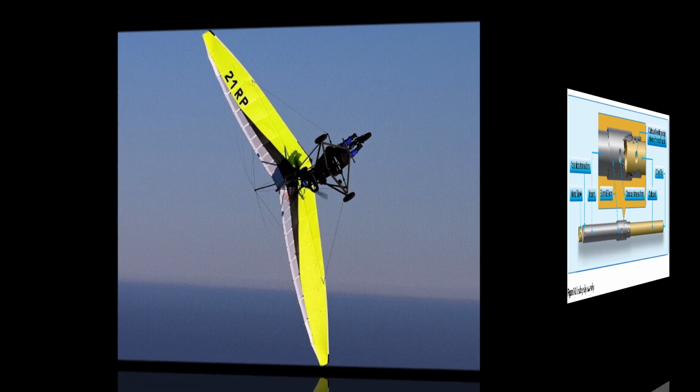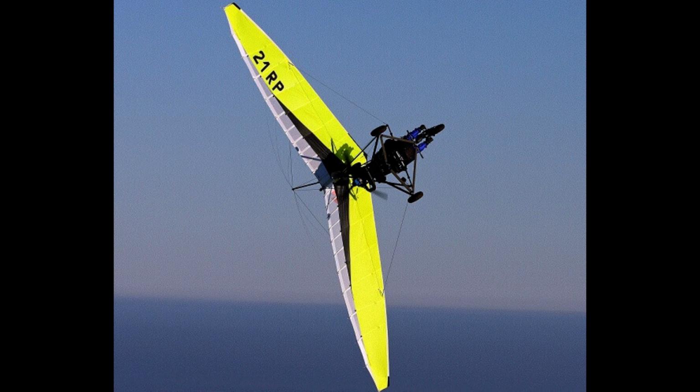Keel. The wing keel is like that of a boat keel, the center of the wing, fore and aft. It attaches to the leading edges at the nose plate and performs a number of important functions. It is the structure where the carriage attaches to the wing, and it is the wing structure that connects the center section of the sail at the keel pocket, discussed later in this chapter in the sail section.